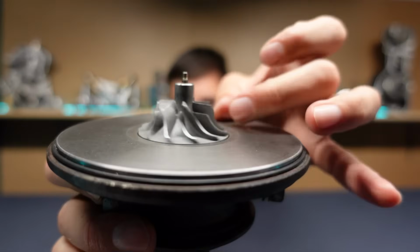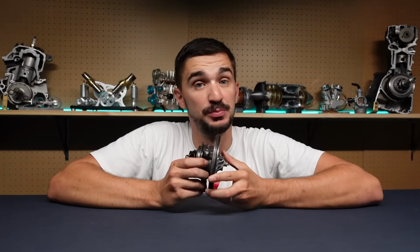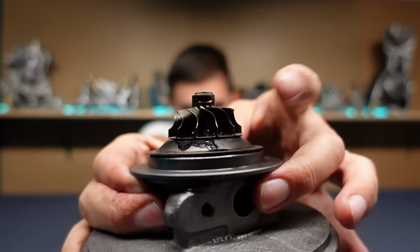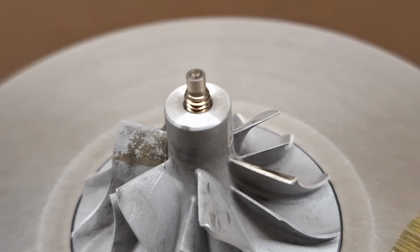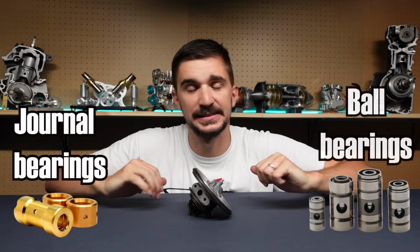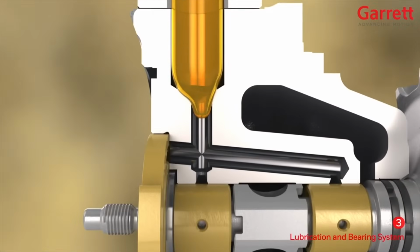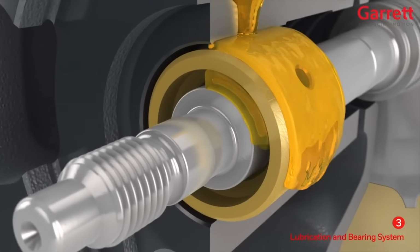Whenever we have something spinning inside of something in a vehicle, we tend to have bearings supporting a smooth and long-lasting rotation, and the shaft inside a turbocharger, which is cast as part of the turbine wheel and onto which the compressor wheel is bolted, is no exception. Turbos can have journal or ball bearings. As a rule of thumb, journal bearings tend to last a bit longer because they bear loads a bit better, but that's only the case if they receive a constant pressurized supply of clean oil, which is changed at regular intervals.